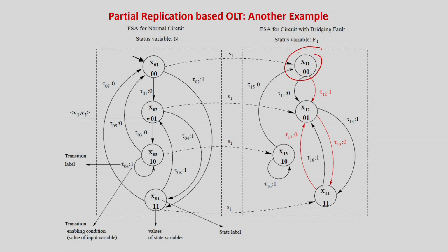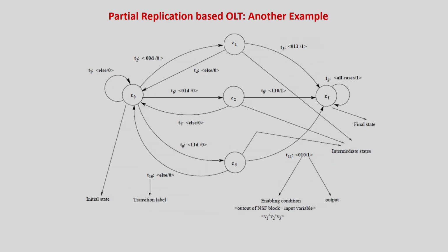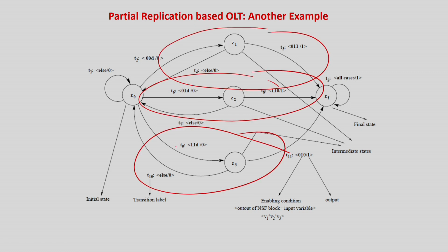So for the same behavior, the same pattern, everywhere you have to track whether this is going to be my state. If it is so, I have to wake up and find out whether in the next state the input is 1 and you are going to this state, then the error is detected. Same idea of FD detector design, but with more FD transitions, there will be more states in the detector machine, so the circuit of the tester will be larger.